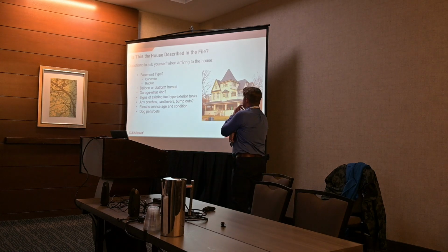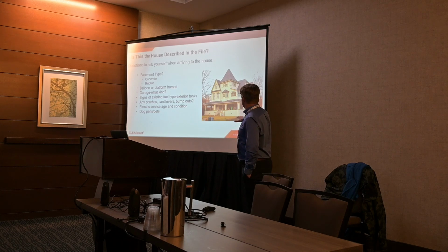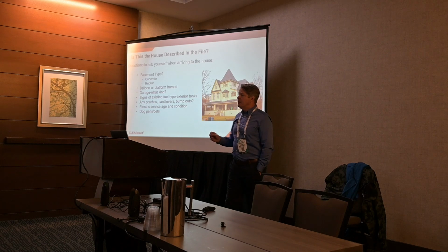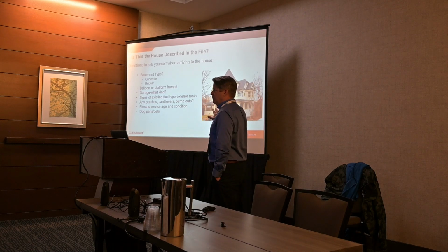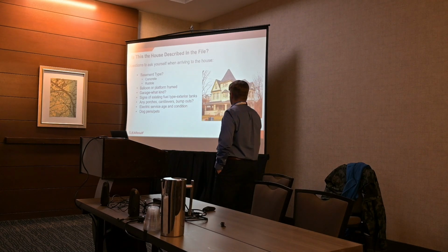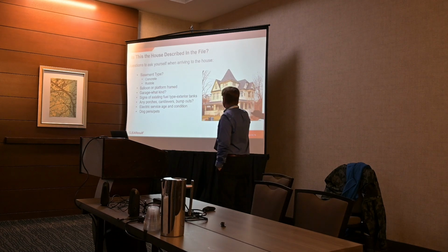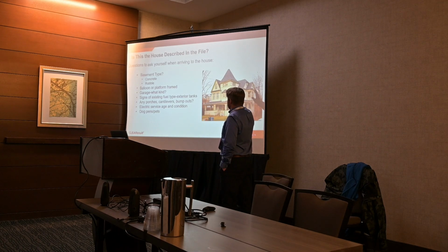For me, basement type is a big thing, right? Is it a concrete foundation or is it a rubble foundation? Because concrete foundations are monolithic, and you can tighten them up if you'd like to. Rubble foundations are a different story. Air comes right through them, and they're difficult to make airtight. Okay, so right away, when you have a rubble foundation, by rubble I mean stone, right? You're going to have problems getting the house tight.